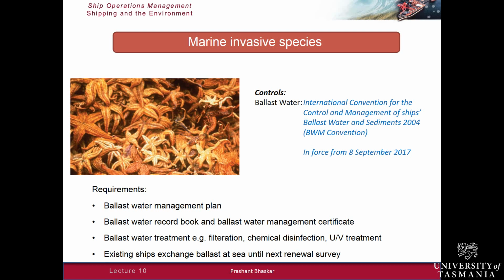What that means is that when they are in port and taking ballast water, when they go out to sea, they should exchange the water that was from the coastal area with water from the deep sea. And the idea there is that many of the coastal species don't survive in deep sea water, and the deep sea water species don't survive in coastal waters. So when the ship comes to the next port and discharges the water which was taken in from the deep sea, it would contain organisms that hopefully wouldn't survive in the new coastal environment.